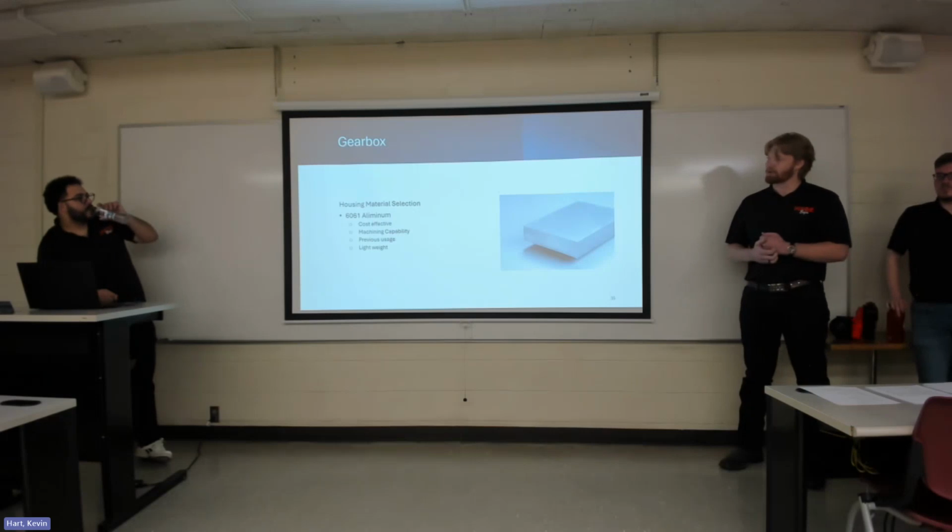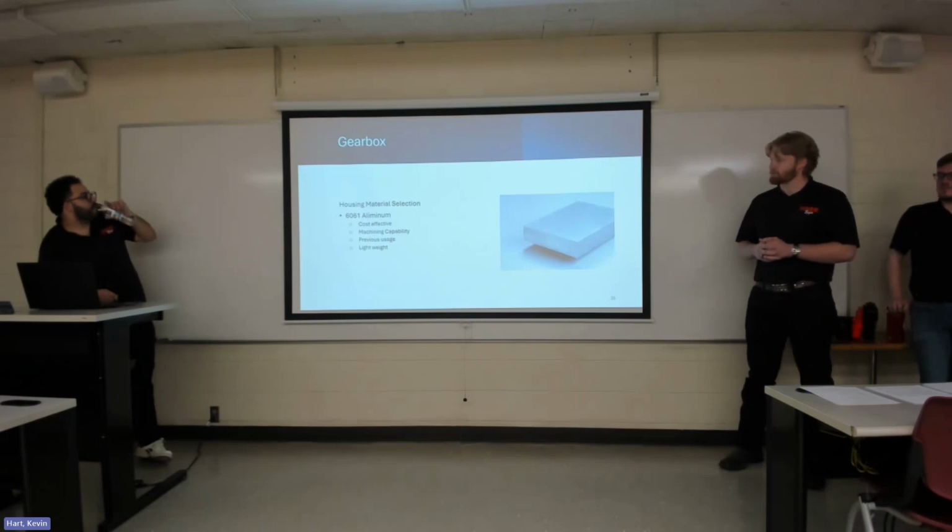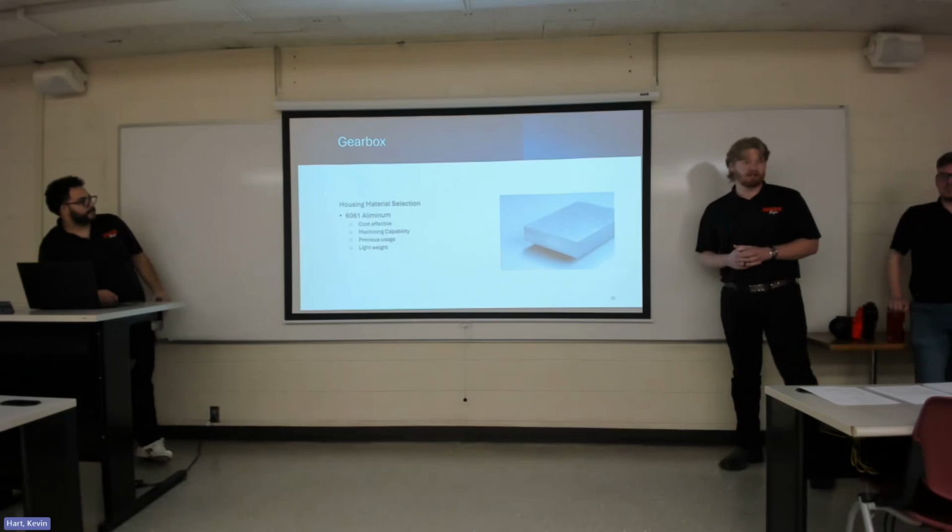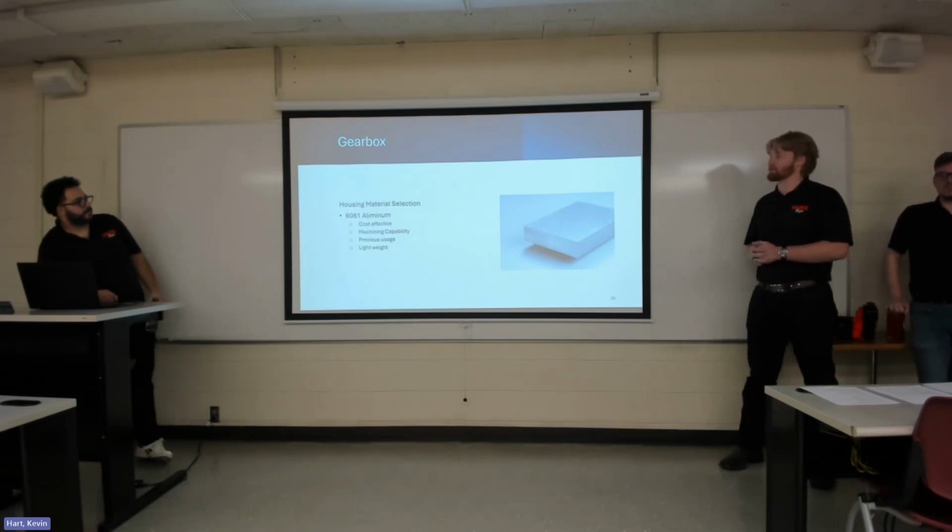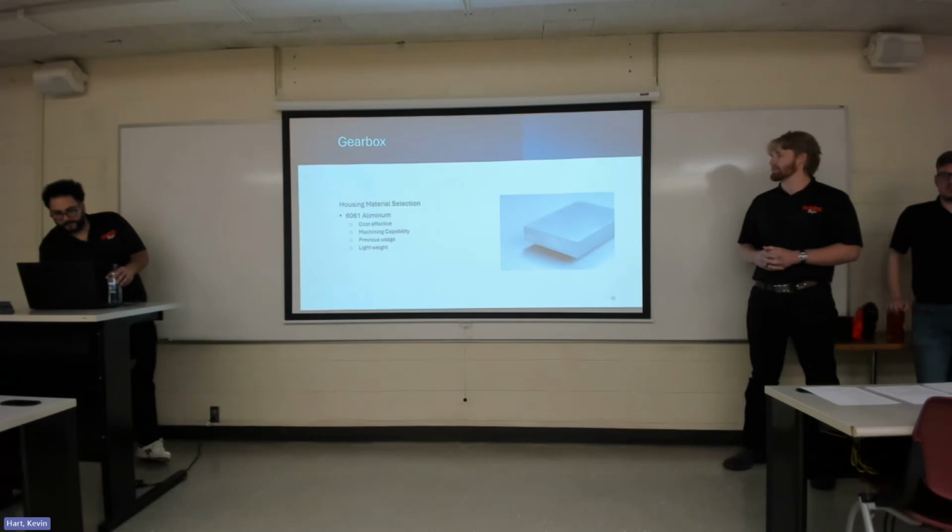And then as far as material goes, we selected a 6061 aluminum, just like everything else basically. We've done it before, basically every single one of our gearboxes has been aluminum. It's pretty cost effective. We can machine it here. Like I said, previous usage, and it's also pretty lightweight for the size.